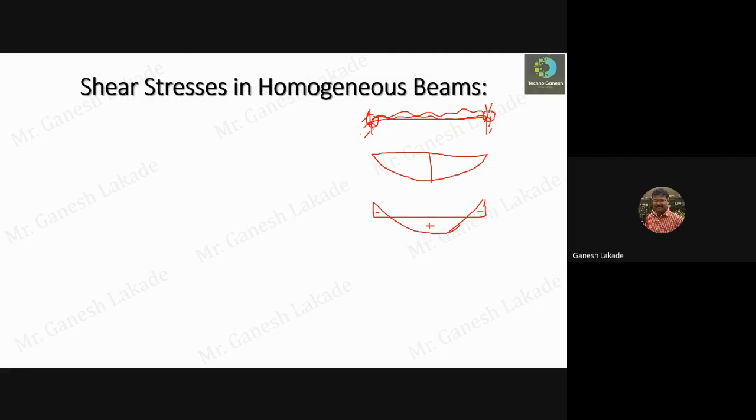So these beams do not act as simply supported beams. There is a partial fixity, so due to that some moment will be there. But that is not part of our discussion right now. We just must know that this is the variation in the bending moment. At one end the bending moment is maximum, at the other end it will be minimum or zero.